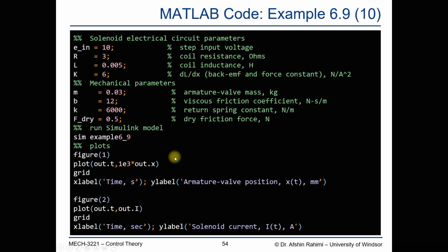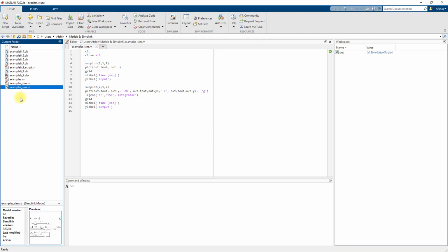To input them, we can write a script that stores these values in the workspace, and then we can run our system model and obtain the results directly using the sim function. Then we can use whatever values are stored in the workspace from the simulation running and plot the information out.